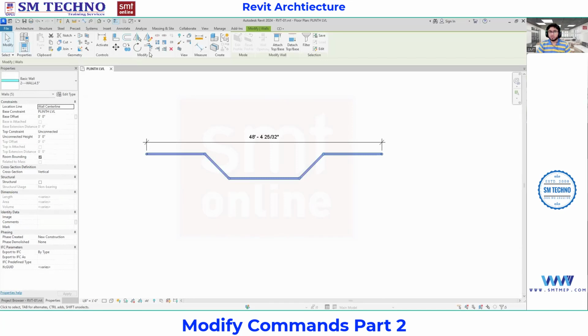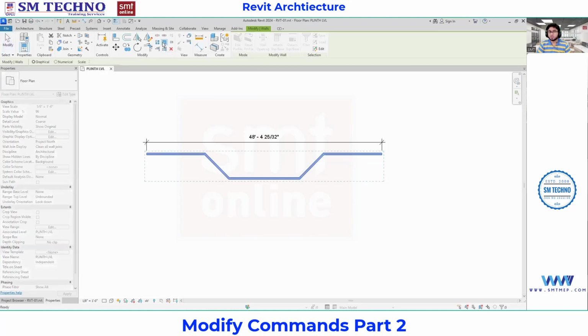So in the Modify panel, we have got an option of the scale. RE is a shortcut by default given by Revit. So select this option. Now you can see in the options bar, we have got two: one is graphical, one is numerical. So I'm going with graphical.